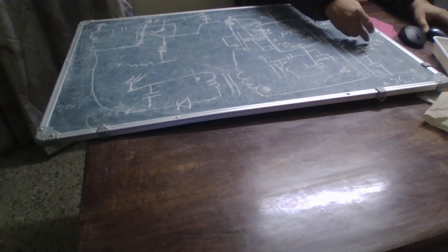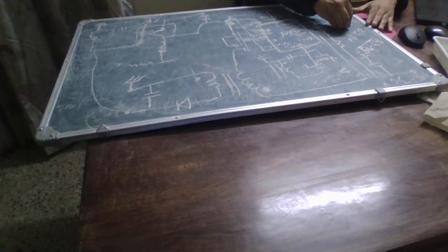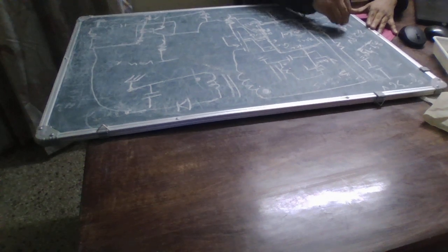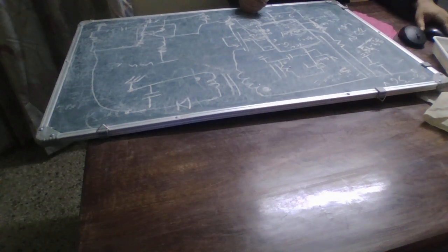So I can power up this IC using a single cell battery, and it can even operate with a low voltage of 1.5 volts. That's what I mentioned, that if the bias pin is greater than 2.9 volts, it can operate with internal voltage as low as 1.5 volts.